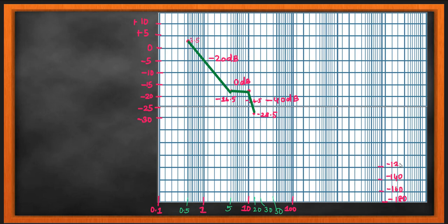You just have to plot these 4 values and then draw a connecting line between these 4 values. And now on my right hand side, I am doing the y-axis for my phase. So depending on the phase values, I've started from minus 180. The scale for this y-axis, in terms of gain and phase, can be slightly tuned to match the table that you get.